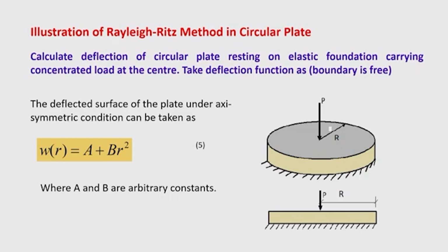So, due to the upward soil pressure, you know that the deflection will be reduced. So, here the subgrade will act like a spring, and this kind of model is generally known as the Winkler plate model, or in the case of a beam, the Winkler beam model.